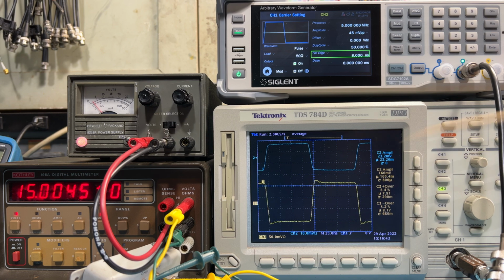But let's see what happens to this waveform as I vary the falling edge. Drop it to 7.5 nanoseconds, you can see that there's some ripple now in the top and a little bit of ripple on the input. So that's probably the fact that as this amplifier goes nonlinear, it's reflecting some of the signal back, and it's not clear whether the ripple in the output is due to the reflections on the input or other stuff going on.